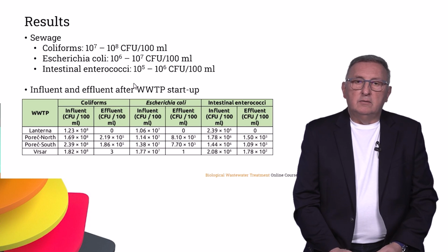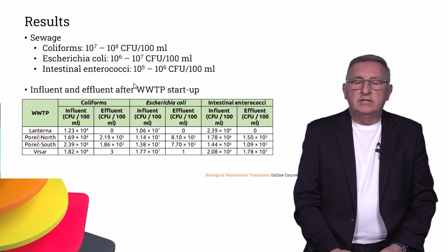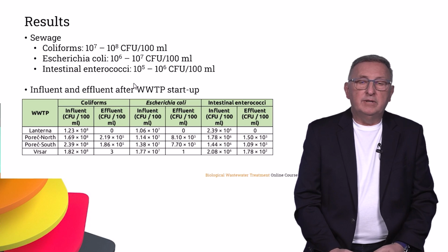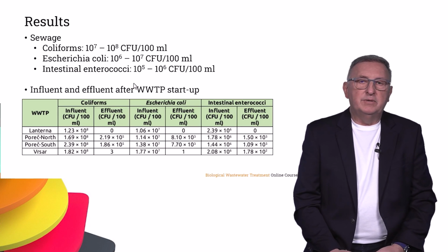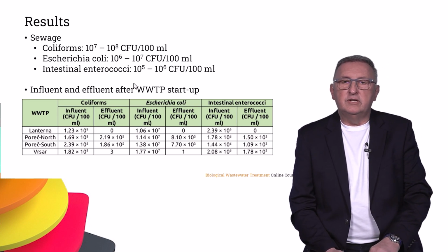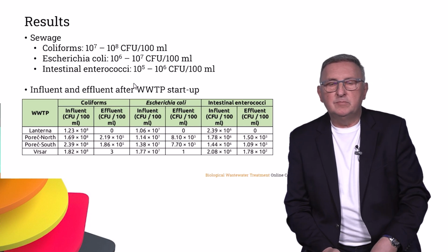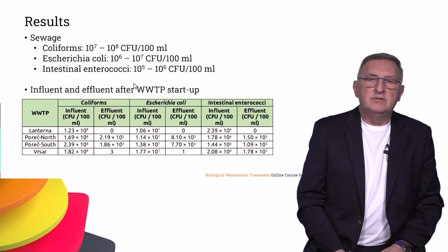So why we have some fecal pollution in this reservoir now is because the treatment plant just started and some of them never discharged the effluent. So there was some regrowth in the reservoirs because the attention during the startup was not really on the reservoirs but on the main heart of the system.